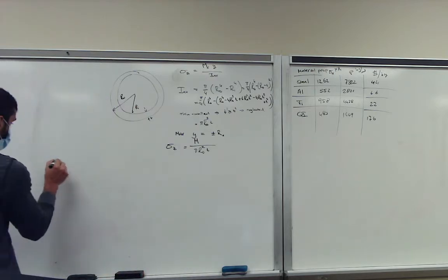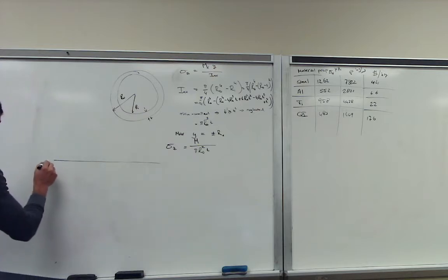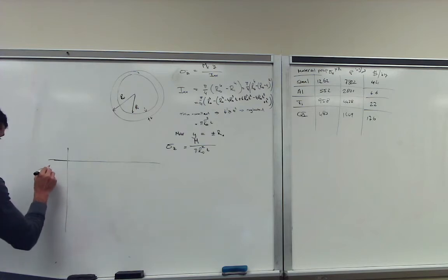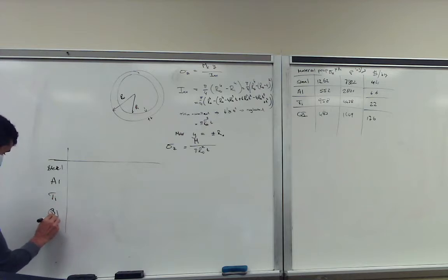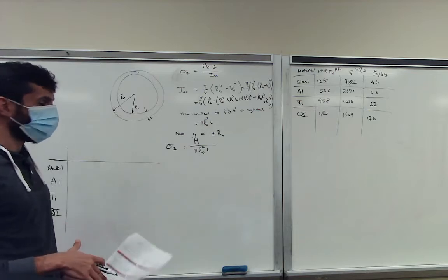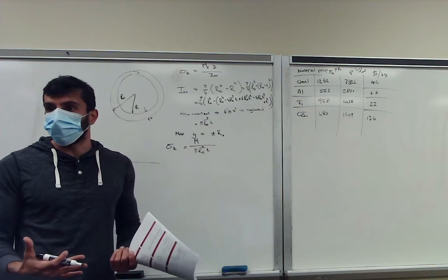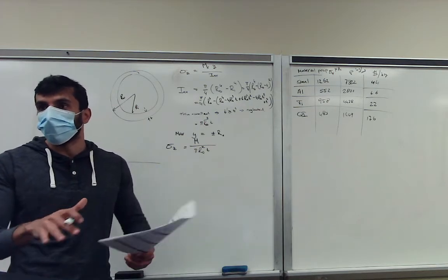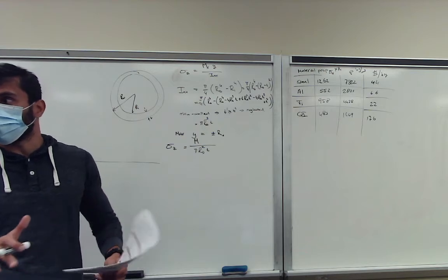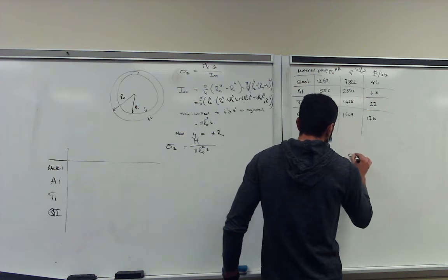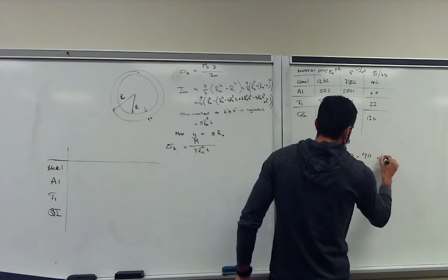Say we are given a moment, so the moment is known, we can rewrite this equation to determine the thickness. So we can make another table based on, again, the four materials, say steel, aluminum, titanium, and a quasi-isotropic. By the way, metals are isotropic materials, and quasi-isotropic means that for a composite, there are equal numbers of fibers in the 0, 90, and 45 directions. Basically, it's evenly split in all directions. So you can make a quasi-isotropic material out of 0s, 90s, plus minus 45.